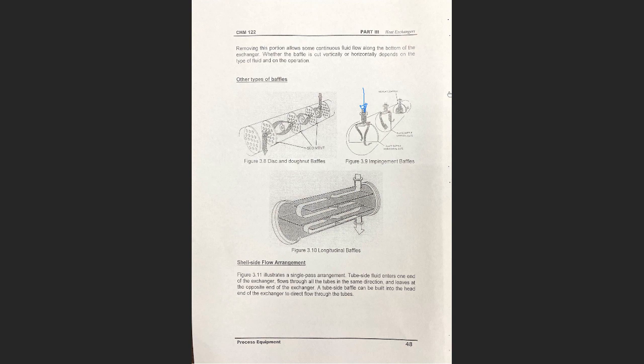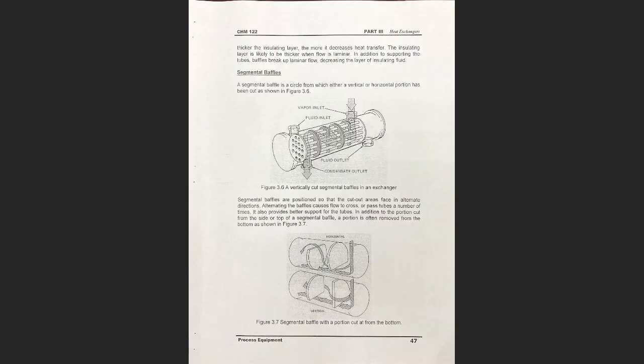And the last thing is the longitudinal baffles, the one we can see right here. Inshallah, we'll talk about it in the next video when we cover the single pass and multiple pass heat exchangers. Guys, sometimes the fluid enters and exits from one side, just like this exchanger. Okay, this is known as a single pass. The fluid enters and exits like this.